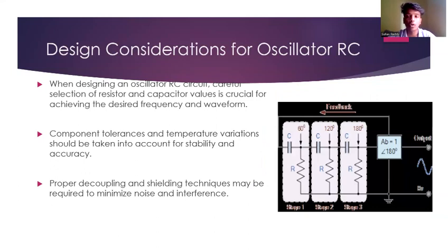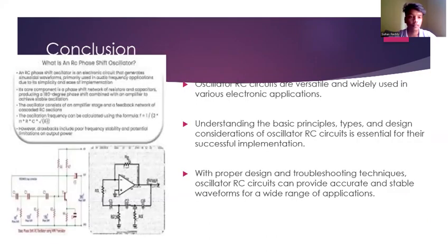Design consideration for RC oscillation. When designing an oscillator RC circuit, carefully selecting the resistor and capacitor values is crucial for achieving the desired frequency and waveforms. Proper decoupling and shielding techniques may be required to minimize noise and interference.